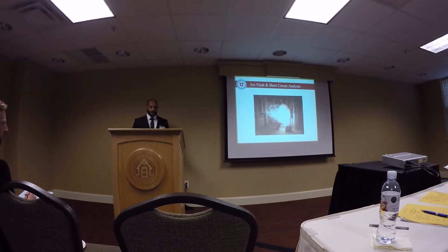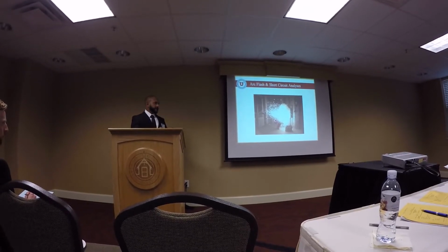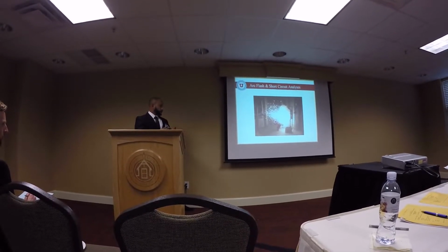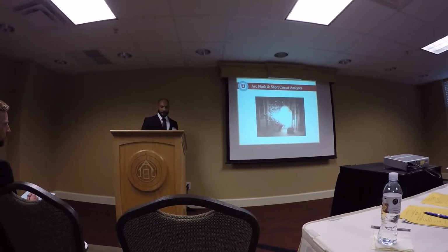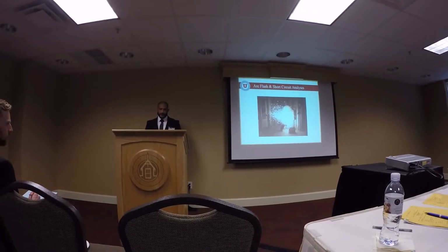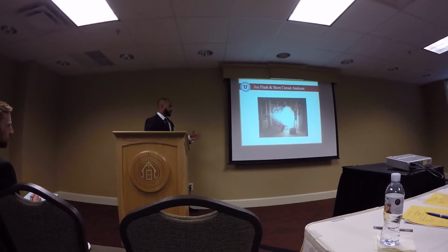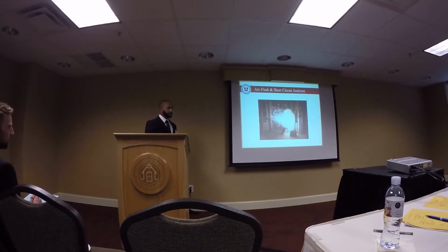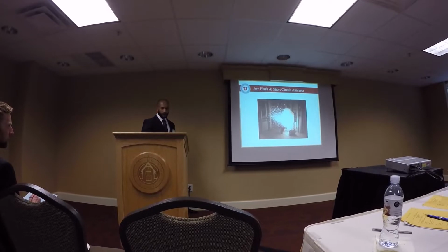What's an arc flash? Arc flash is a phenomenon where the inrush current leaves its intended path and finds the easiest way through one conductor, air to another conductor, or through a human to ground. So doing a short circuit analysis gives us an indication of how much risk there is at each breaker and each panel, so we can address that going forward.